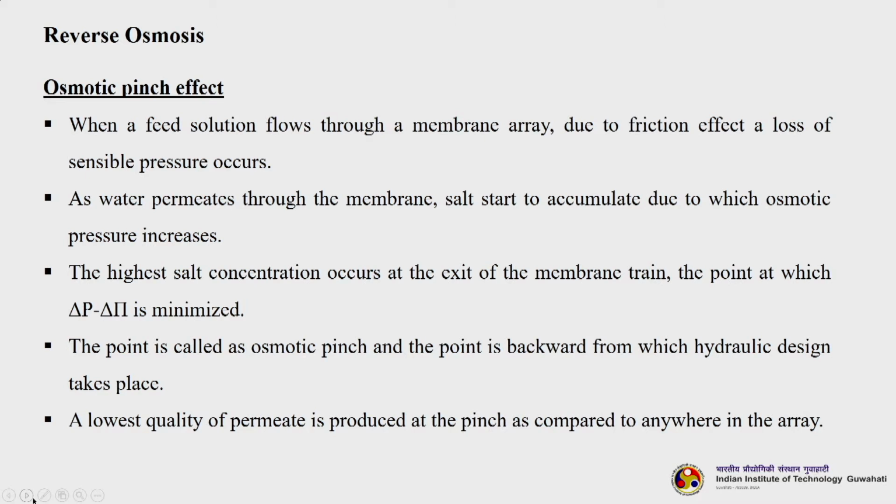The highest salt concentration occurs at the exit of the membrane train, the point at which delta P minus delta pi is minimized. That point is called the osmotic pinch, and it is the point backward from which the hydraulic design actually takes place. The lowest quality of permeate is produced at the pinch as compared to anywhere in the array.